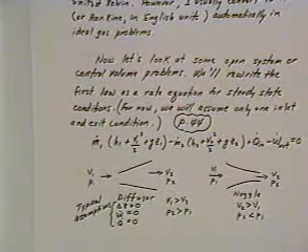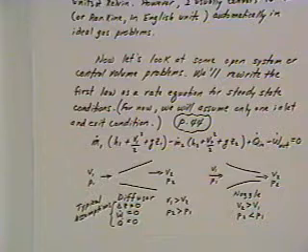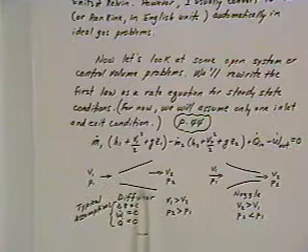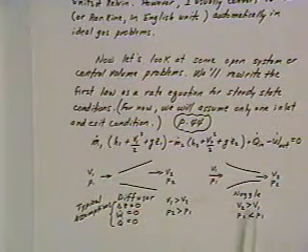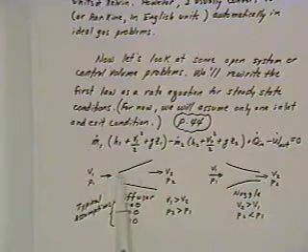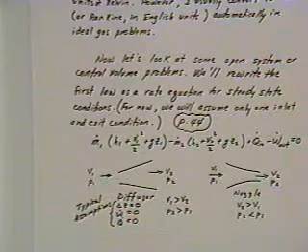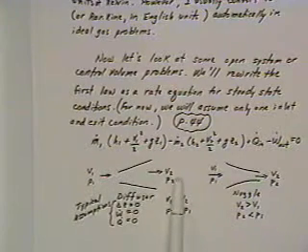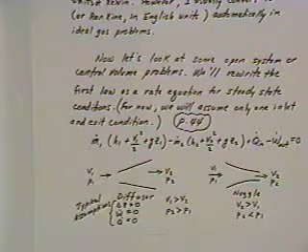Okay, now there are a couple different problems here that we'll work out involving first law examples for open systems. We'll start out first of all with a diffuser, and then secondly a nozzle, and let's go over the assumptions that you're typically going to be making in these. If you have a horizontal device, such as a nozzle or a diffuser as we've drawn it here, the entering potential energy and the leaving potential energy are going to be the same. They're at the same elevation, so the change in potential energy is equal to 0.